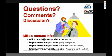Robert says, based on what I've heard tonight, CHT gauges are more important for leaning. So, for what use would an EGT gauge be? Again, my philosophy of using this stuff is that EGT is primarily useful in troubleshooting problems. First of all, detecting various kinds of engine anomalies, and then in troubleshooting those anomalies. It's not a good thing to use for operational control of the engine. Its primary benefit is in detecting and troubleshooting problems.